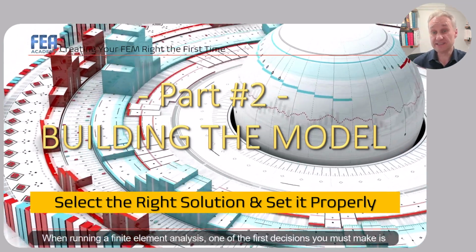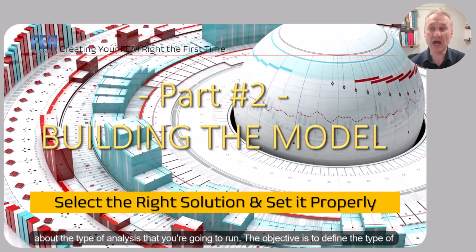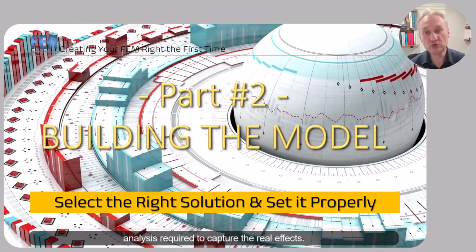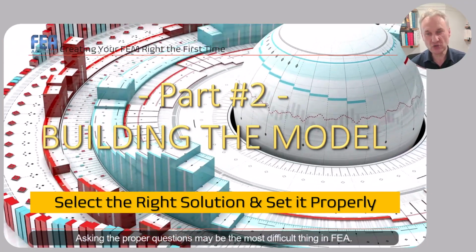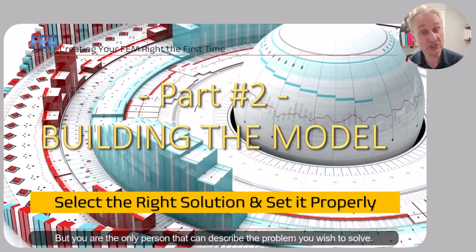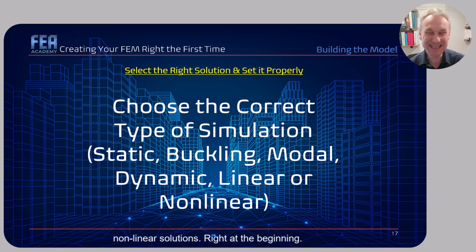When running a finite element analysis, one of the first decisions you must make is about the type of analysis that you're going to run. The objective is to define the type of analysis required to capture the real effects. Asking the proper questions may be the most difficult thing in FEA, okay? But you are the only person that can describe the problem you wish to solve. So, you will have to choose between static, buckling, modal, dynamic, linear, or nonlinear solutions, right at the beginning.